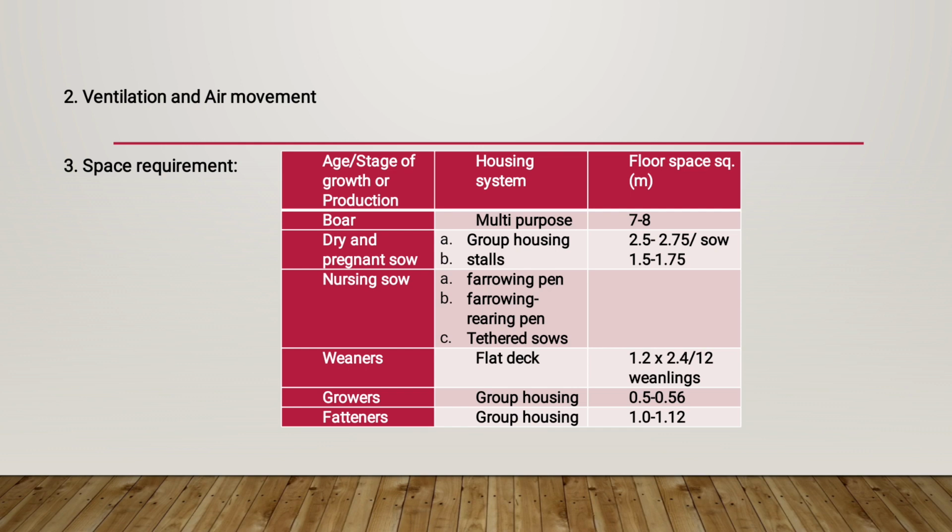Okay, next, we have ventilation and air movement. So, depending on the age of the pigs, number of pigs housed, temperature inside and outside, ventilation has to be regulated. The aim of ventilation in summer is to limit the temperature rise inside the house, and summer ventilation rates are calculated to set a temperature limit of 1.5 degrees Celsius to 3.3 degrees Celsius above the outside average temperature as an acceptable minimum in the house. So, installation of electric fans ensured good ventilation and air movements during summer.